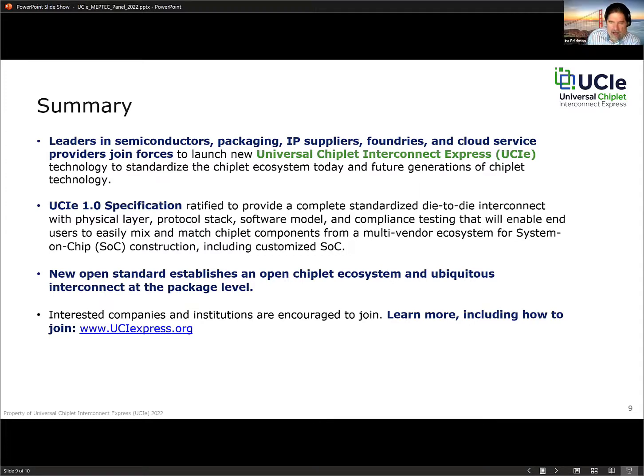Thank you, Devendra. Some quick questions. You talked about the physical layer. You talked about the bump pitch. So is the bump pitch and the pinout defined for each of the 2 different types of packages? I mean, are those nailed down by the spec, or is there some flexibility? Yes. So we define the bump map for each of those packages in the UCIe spec. And the other interesting thing is that within those ranges that we have defined, you can design a die with 25 micron and another at 55 micron, and they will still interoperate.